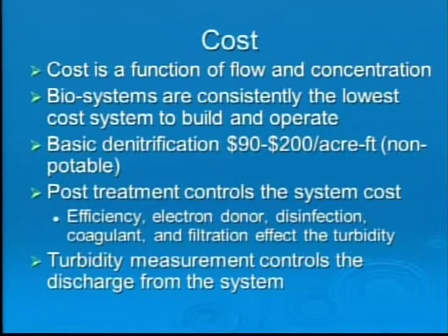The work we did for EPA at Bendina, we used methanol as an electron donor. Methanol is a great material for filtration. We were not going to be able to operate a methanol system in California. So that dramatically changes the filtration requirements of the system. And they're all interactive because as you change the efficiency of filtration, you change what's going to happen in terms of the disinfection. And when you change the electron donor, you're going to change across the whole system.